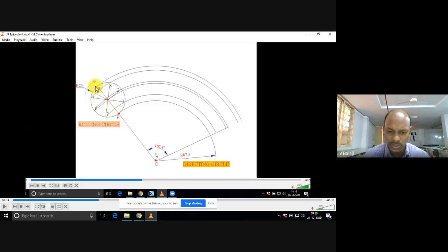Now we come to dividing the angle. Take your protractor again and mark 11.6, starting from the OP line. OP line is the starting line. Can you divide with your protractor? So you can easily divide, right? Just calculate. If it is 11.6, draw so many parts. Extend those lines up to the center arc.